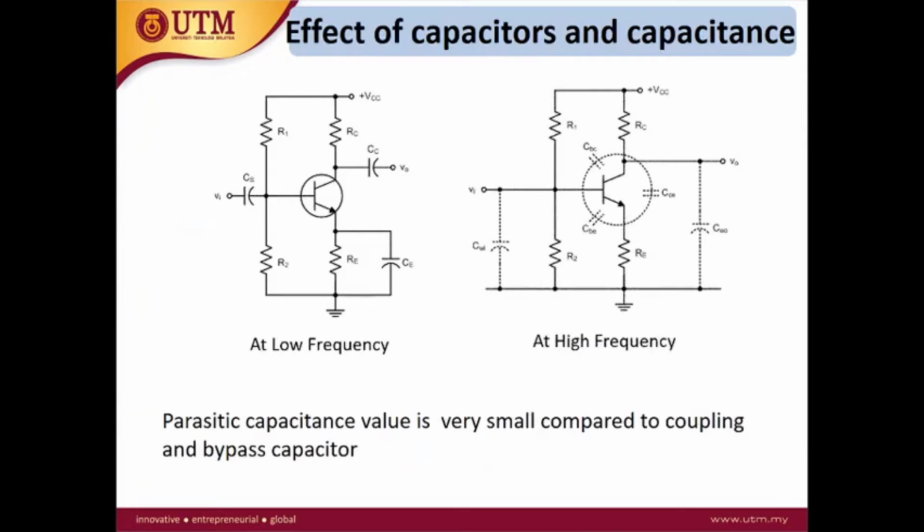Okay, the statement in the previous slide can be shown from the circuit. So this is what happened at low frequency. At mid frequency, we will replace the CS, CC, and CE with the short circuit.